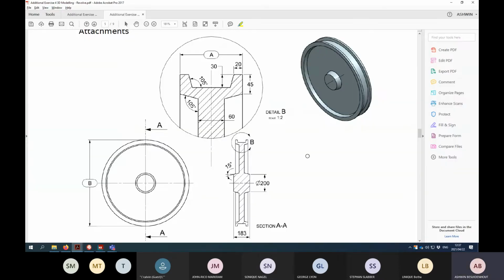Don't get me wrong. This specific sketch can be done by using extrudes as well. But let me tell you this, it won't be smart to do that. When something is round, you can create a solid disk, and then you can cut out some of these sections. You can put in a cut extrude here, then you have to manage the begin and end conditions to get this section here. Then you need to put drafts on it as well, so that you can have the specific draft angles, or you can put in a chamfer there. But that's unnecessary. It's a lot of work.